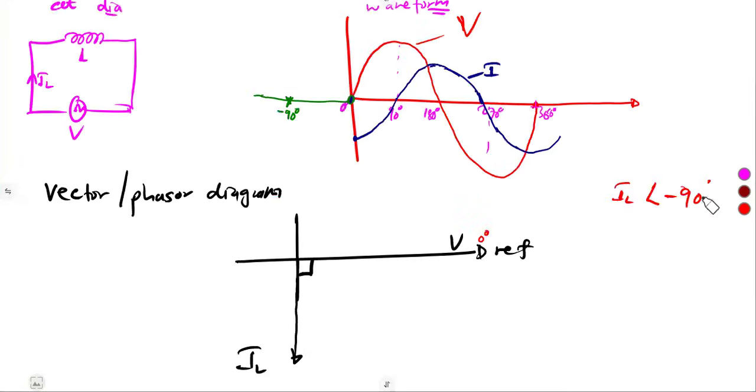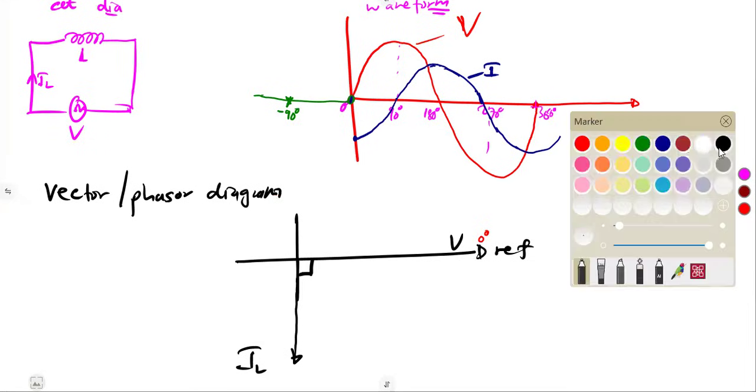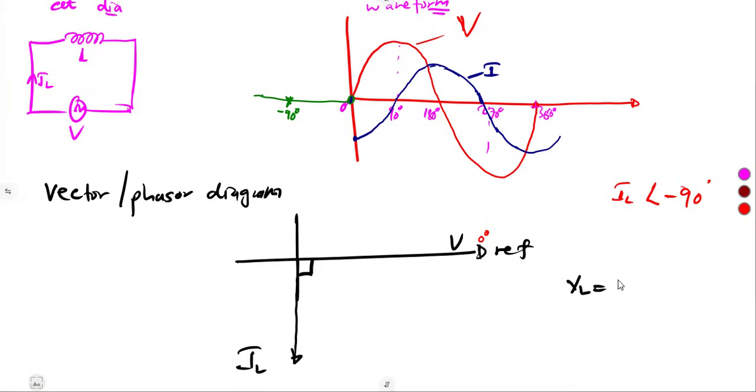So using this, you can also consider capacitors. For capacitors, I'm just going to rush through since we already have inductors. Do not forget your calculations, guys. When you're dealing with an inductor, the calculation of the reactance XL is 2 pi FL. With the reactance, we can calculate the voltage drop across the inductor, which is our VL, from the total current, as we understand that this is the total current that we have.